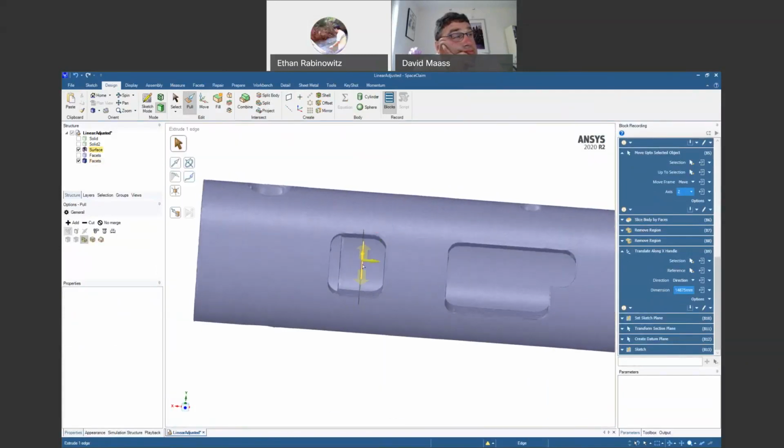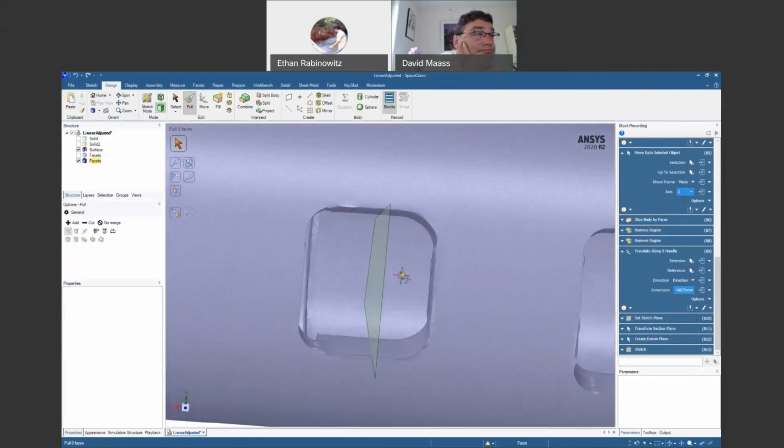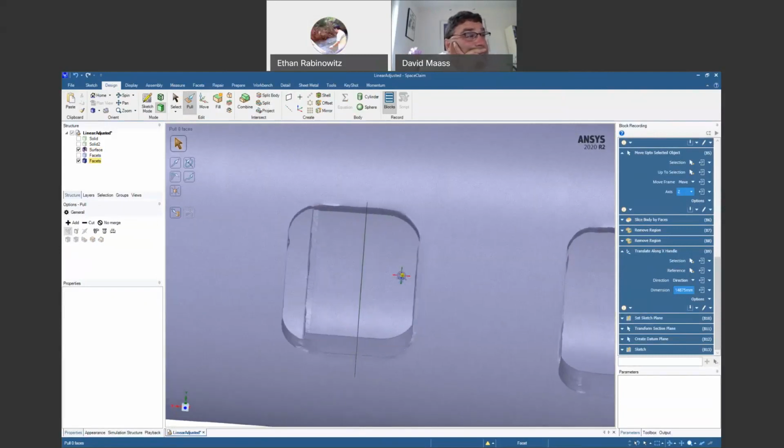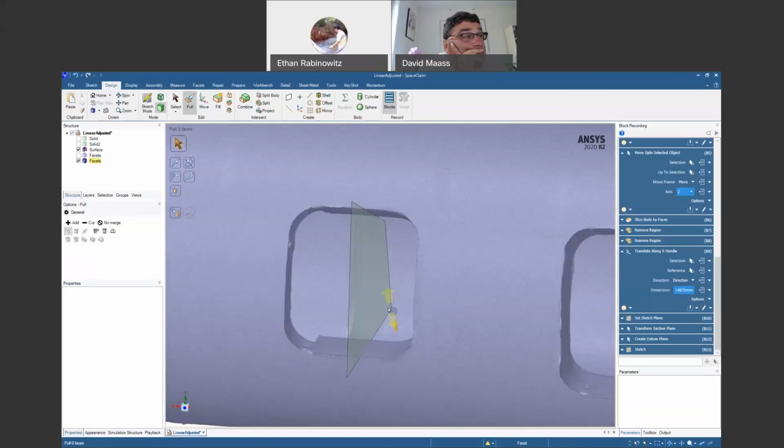And from here, we could think about this in a couple ways. One thing I could have done, had I set up a datum plane on this face and then sketched right down the center, is a symmetric cut where we pull it in both directions. I wasn't thinking about that when I got here, and doing that would add steps to add the datums, etc. The option I have now is to simply make a cut in one direction and then a cut in the other direction.